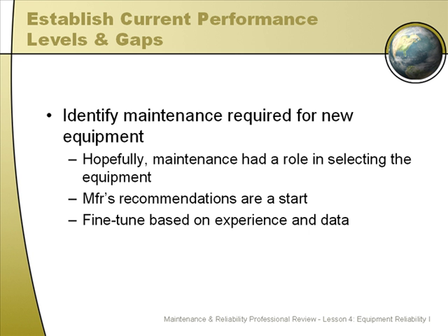Second, manufacturers' recommendations are a start. Usually the manufacturers have recommendations for how maintenance should be carried out on their machinery. You don't need to read it like it's the Bible, but you can take it as a starting point and refine it to meet the needs of your production process.